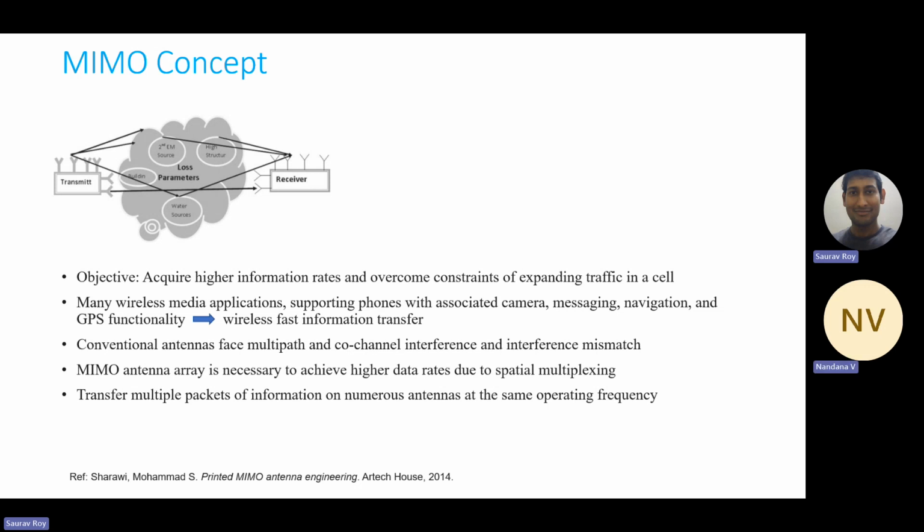So this phenomenon in MIMO is called spatial multiplexing. Multiplexing means we do it over different scenarios, multiply it. That is why it's called multiplexing. And it happens spatially because with these 4 defined antennas, the waves will propagate in 4 defined channels. So that is why it's called spatial multiplexing. Understood, right? So this is one very important scenario.